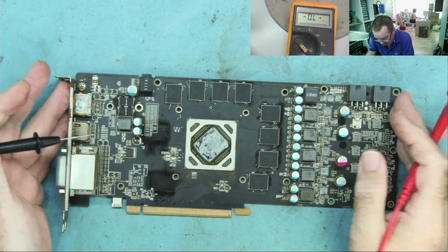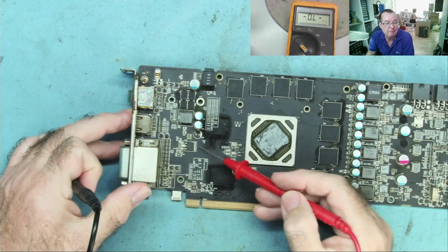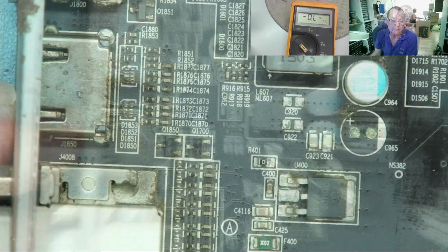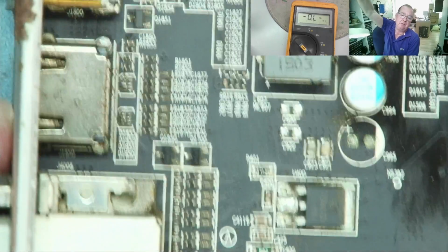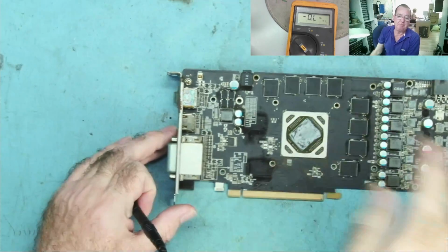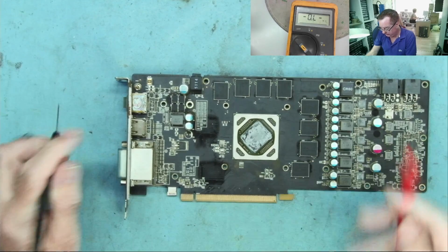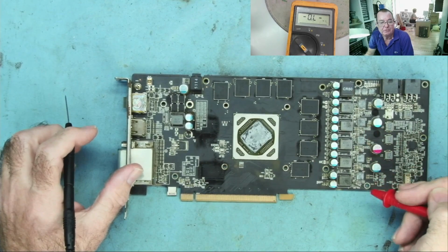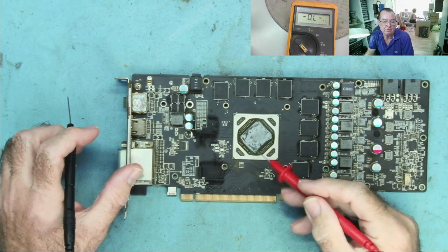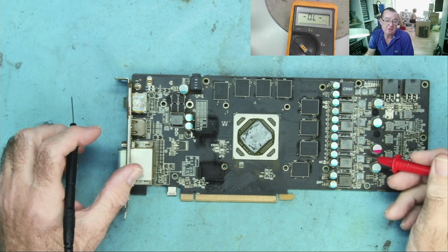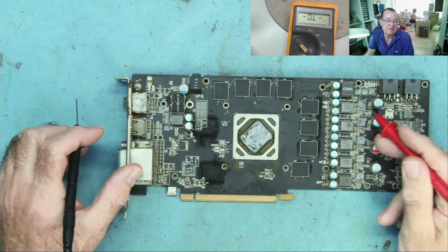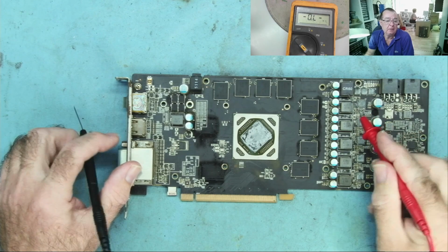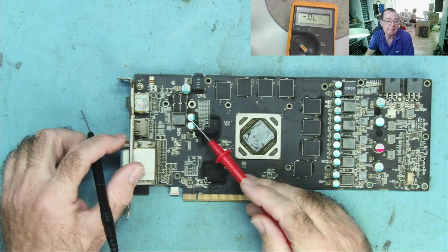Let's have a look at the other card. Looks different, but we got pretty much the same thing. Something that looks like a voltage regulator there. Yeah, 78M05 again, so that's your 5 volt. You know straight away. So now we need to find everything else. Well, these 5 all the same are probably on the V core. That's what draws the most power. So you'll often find 2, 4, 8 altogether, 5 on this one. We have one there that's different. Okay, we have another one here which is different.